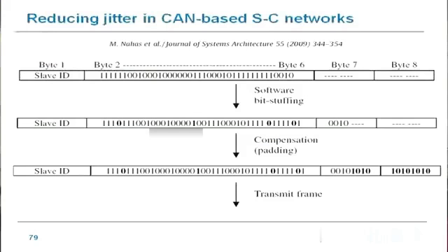So one possible way of dealing with that is that you manually do software bit stuffing. If you take control of the parts of the CAN message you've got, you process them yourself, and you effectively ensure that the protocol won't introduce bit stuffing that you cannot control, then you can reduce the level of artificially induced stuff bits in the message transfers.